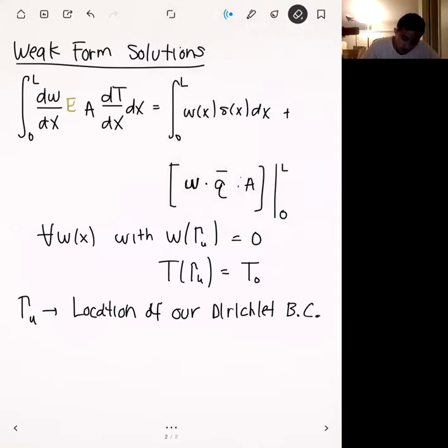we'll have the Young's modulus. And of course, instead of temperature, since you don't solve for temperature in elasticity, what you have instead is the displacement, which we use the symbol U for. Also, instead of a thermal generation function, we have a body force function, which is usually given the symbol B of x. And instead of a heat flux, what we have instead is a traction boundary condition.